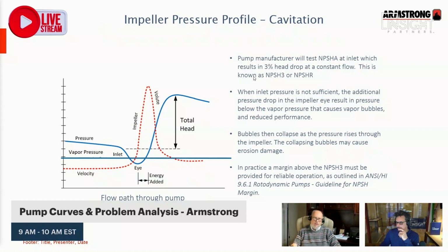There's a lot of great information in there, and if you really want to understand pumps and fluids, you'll learn way more than you ever possibly could have wanted to know. But if you read 961, that talks about the HI standards guideline for NPSH margin, and it is 30%.